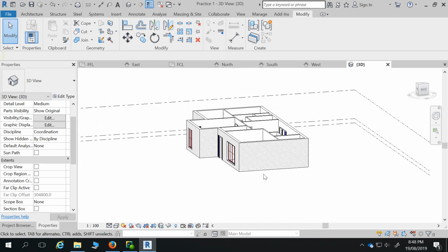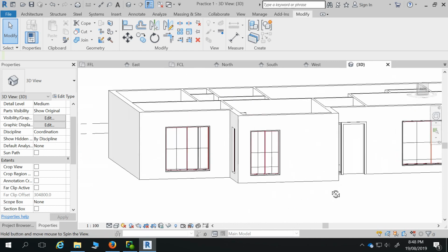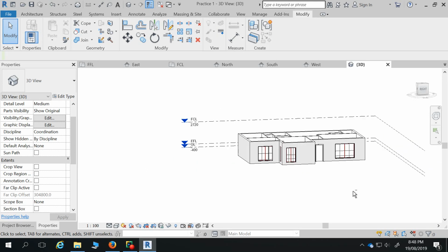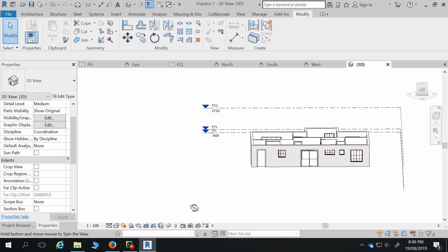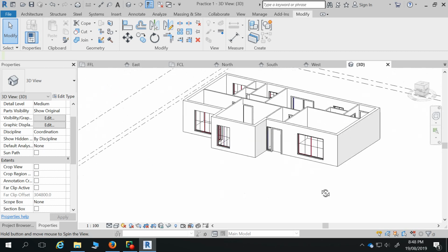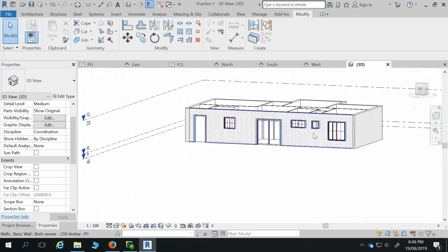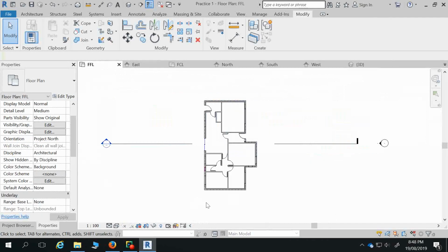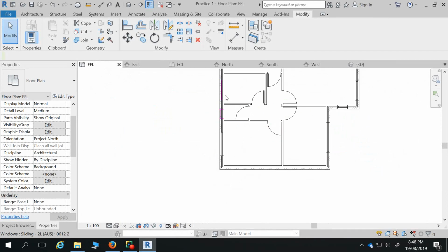When you're building with a brick house, brick veneer type situation, you've got to pick a head height where you want your windows and your doors to finish based on brick heights, because you don't want it to finish halfway through a brick. So depending on your rebate and how you've worked it all out, you'll pick something that's going to be quite uniform. The other thing that throws up, and someone had already done this, that the question came up, is when I've got those up to that head height here, some of the smaller windows in the bathroom, if I look back at my finished floor plan, have now disappeared.